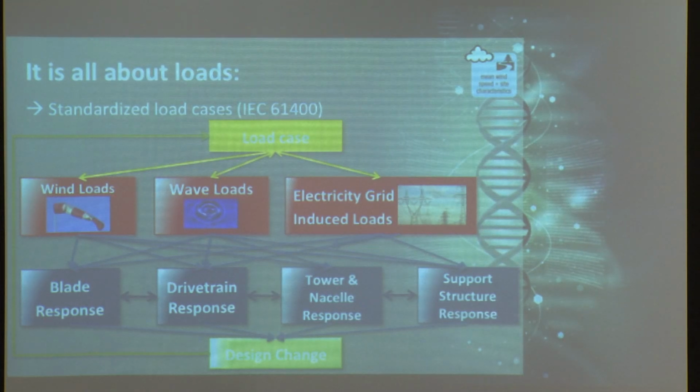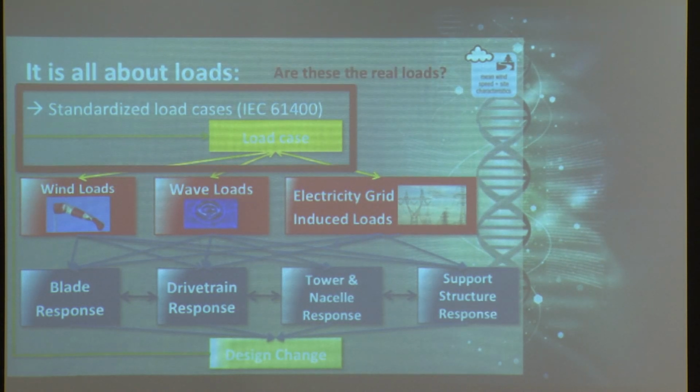Based on these loads, you calculate the strength of all components. You will make a design, go through the loop again, see whether it's improved, and so on until you're satisfied. So it all starts from the loads. Of course, you need to be sure that these loads are the real loads, otherwise you design for something that is not the real thing, and you could experience failure.